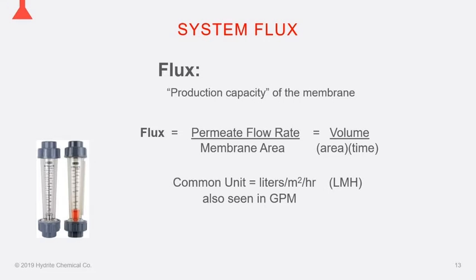And you'll see on the left-hand side those analog rotometer gauges. And if you're lucky enough to have a more modern system, or people that spend a little more money, you'll have electronic flow meters, which are always great because those don't have any variability, and you can read a more accurate reading, in my opinion.